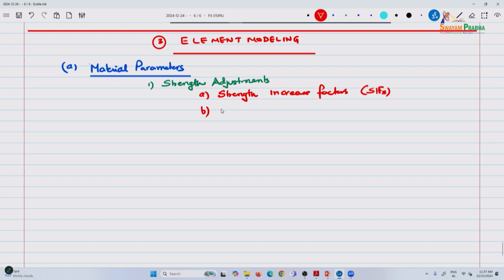And then even the same case with steel, right? When you have steel, you say it's 415 megapascals, that's just a standard. You test it, you might get definitely much more than that. So you have to account for those also. And just like in seismic, you're evaluating the capacity of the structure at its limit. And then you also have what are known as dynamic increase factors.